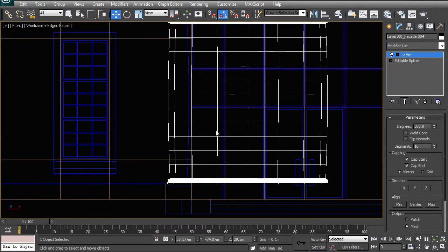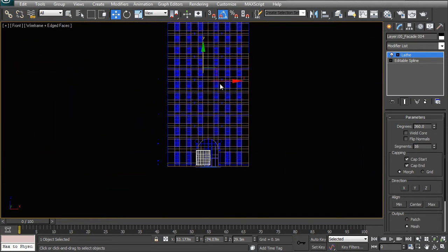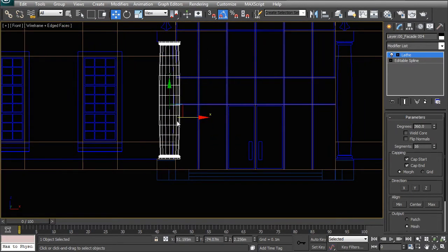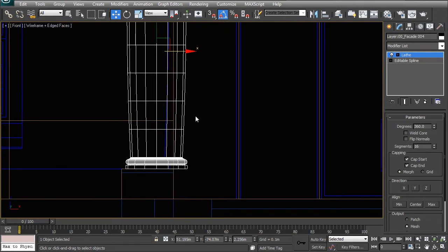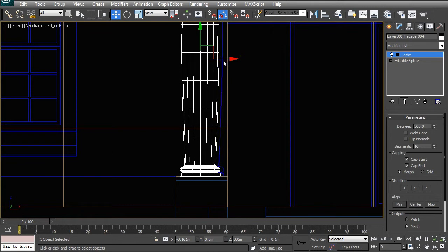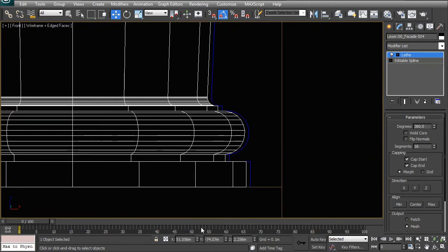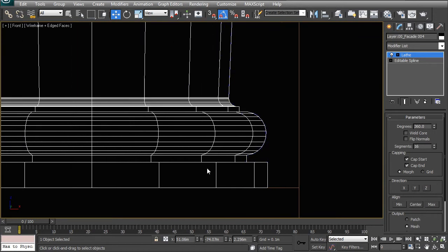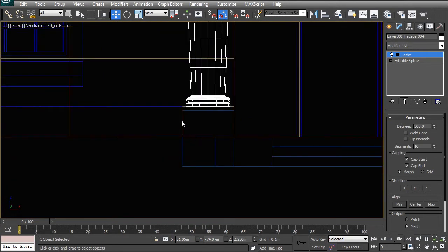And what you would want to do now is right click and then with your axis just adjust where that axis is. Now I'm going to move that in manually, but if you really do want to be precise, you can have a look at what the coordinate is for the halfway distance between the two maximum points. So I'm just going to do this by eye, since I'm not too fussed about getting this too perfect. So I'm just going to use the spinner to manually click up until I see that shape being correct.